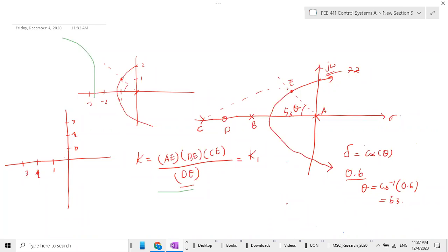And then last clarification. Yeah, so you said that this root locus just shows how we vary k. So that means, for example, if our k ranges from 0 to 72, where it intercepts the j omega axis, that is for 72. Yeah, 72, remember? And then you remember we got that.